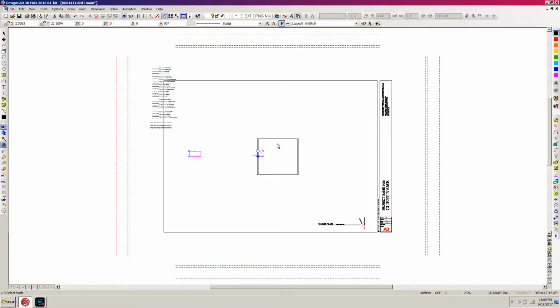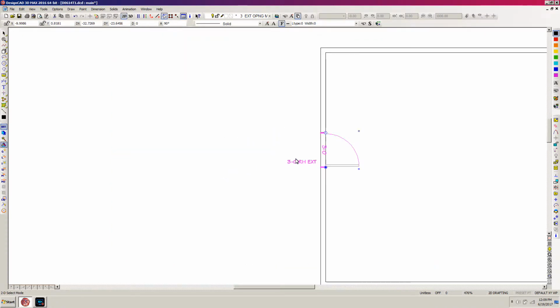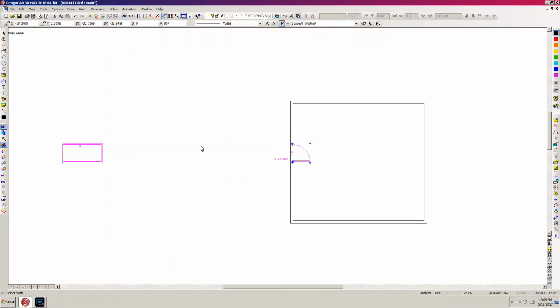Okay, so now I'm going to want to move the whole thing down a little bit, actually 19 inches, and the reason I'm going to want to do that is because the door rough opening is 3'2" or 38 inches, and half of that's 19. So I want the center of that door to be centered on that wall. So now I'm going to zoom up in that area so I can see it a little more closely, and I think I'm going to go ahead and explode this symbol. Well, I'll go ahead and move it.